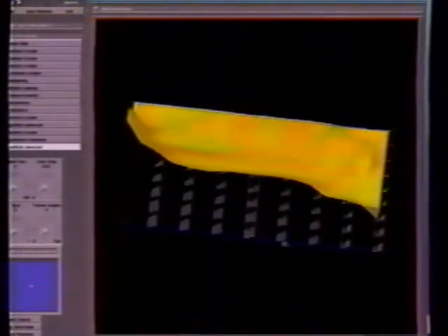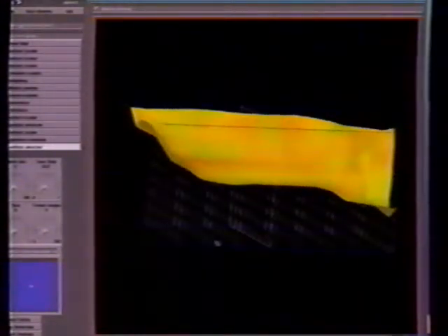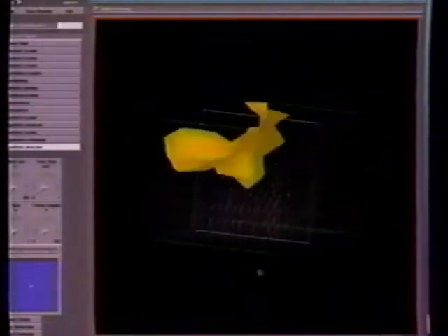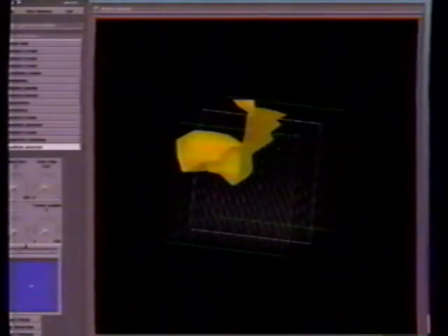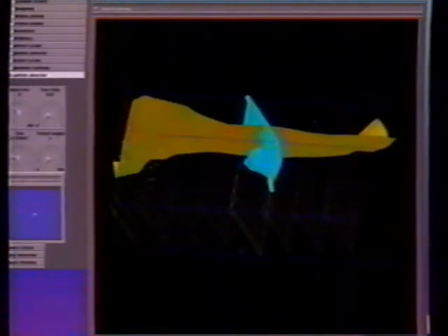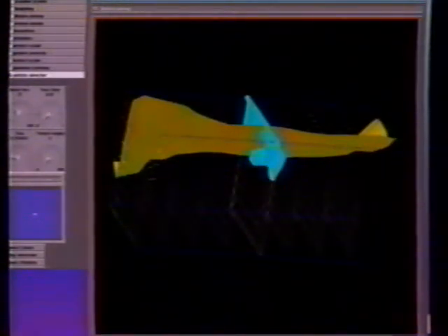In addition, we have the ability to advect particles into this system to see how the flow proceeds. There is a rectangle, which we are now highlighting with the mouse, and within this rectangle, particle flow will be displayed. Here, a batch of particles has been released within the rectangle in question, and we are watching them advect using a forward Euler technique.